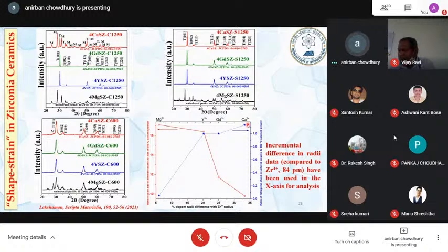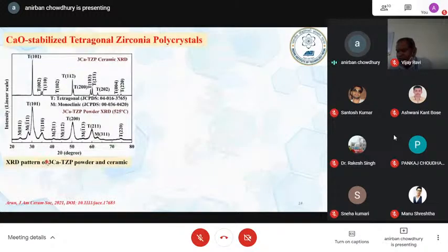So less than half, or 1/4, of their amount we are using, and we are making this tetragonal phase stabilize. Tetragonal phase, as I said, is important for dental applications, mechanical properties, thermal barrier coating, and many others. We are using this tetragonal phase stabilization using calcia doped zirconia, 3 to 4%. We took this work forward, and we are showing here with 3%.